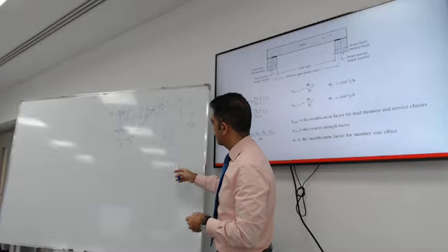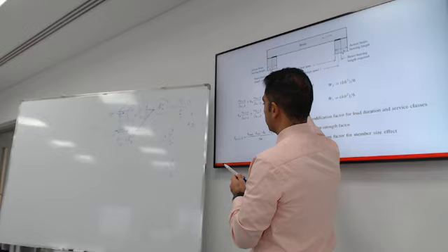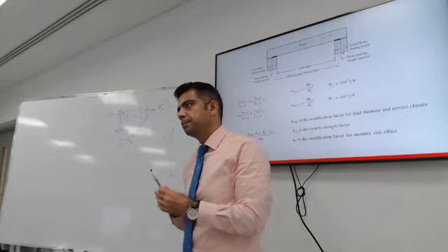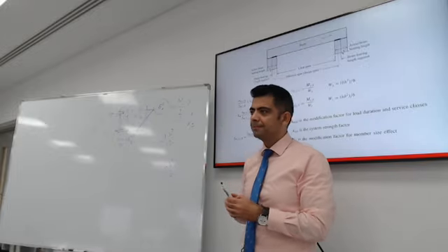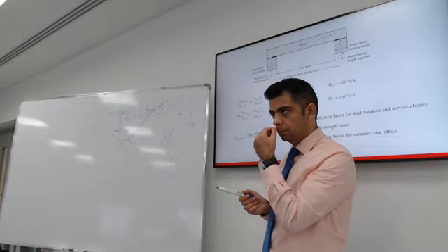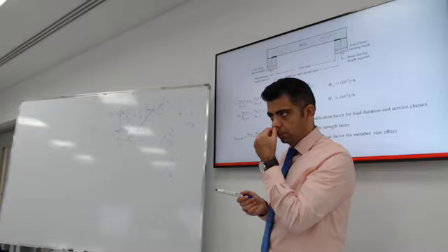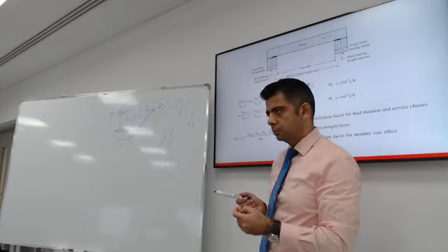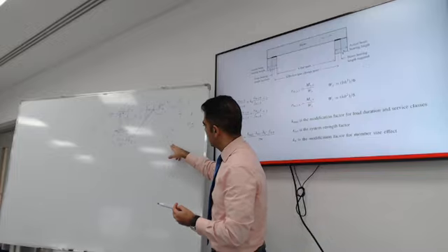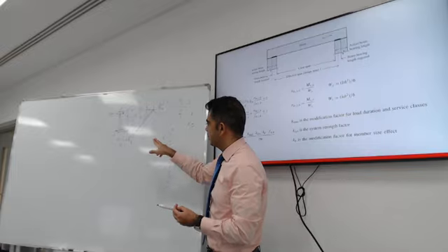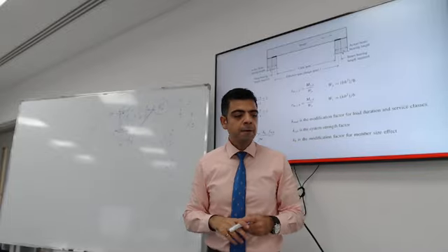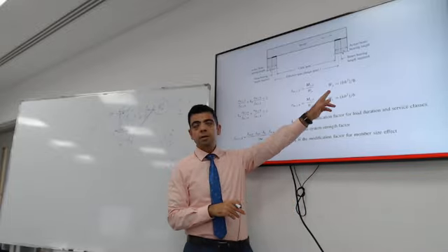We're getting the section modulus W. From this equation, it's going to be B over 2 divided by A B cubed over 12, right? So one of the B's is taken away, but I don't understand where we got the 6. Because the 12 is in the bottom and the 2 is going to be in the top, so you can do the math and it will become 6. So that's what the code says about the section modulus.